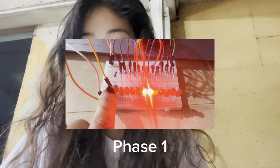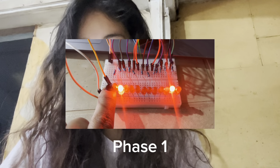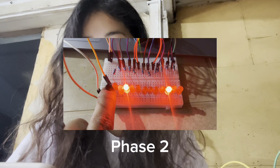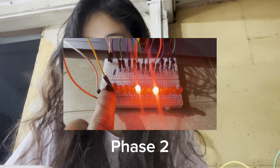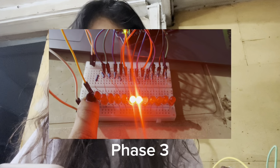The first phase is a mirrored expansion effect that begins at the center of the LED array and moves outward. In that phase, 2 LEDs at equal distances from the center are turned on simultaneously. The second phase is a mirrored collapse effect that reverses the direction of the movement. Instead of expanding from the center, the LEDs begin lighting from the outer edges of the array and move inward toward the center. The final phase introduces a skip burst pattern, which adds complexity and uniqueness to the display. In that phase, every third LED is turned on and the starting position shifts with each step.